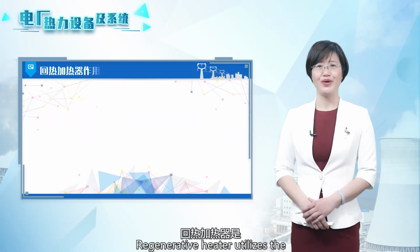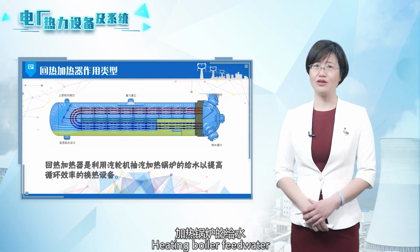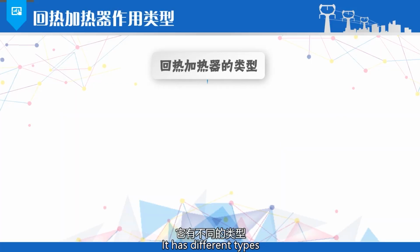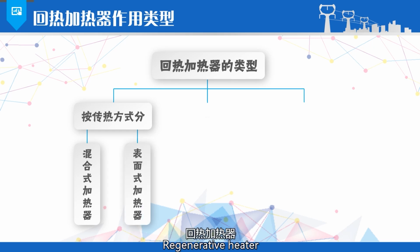Regenerative heaters utilize the extraction steam from the steam turbine to heat the boiler feed water, a heat exchange equipment used to improve cycle efficiency. It has different types, classified by heat transfer method. Regenerative heaters can be divided into hybrid heaters and surface heaters.